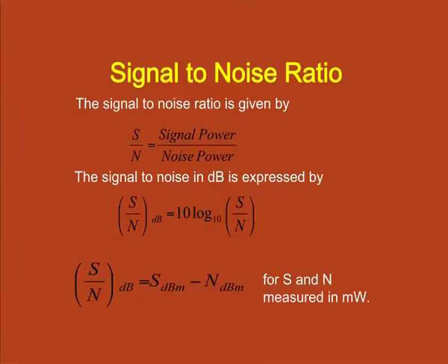Here we will try to correlate the fraction of signal energy we should be considering for defining bandwidth. We have already understood that signal bandwidth is defined only for signals of finite energy. If we want a larger and larger fraction of the signal energy to be considered, we will have to go for a wider frequency range, which will lead to a linear increase in the noise power. It means that if we go for a higher fraction of signal energy, we might end up with a lower signal to noise ratio. So, there has to be a trade-off in the fraction of signal energy we are interested in, based on the signal to noise ratio we want at the receiver side. We cannot keep going for higher and higher fractions of signal energy, because ultimately that will lead to a poor signal to noise ratio. At the same time, we cannot go for a very small fraction of signal energy, because then the signal might be below the sensitivity level of the receiver.